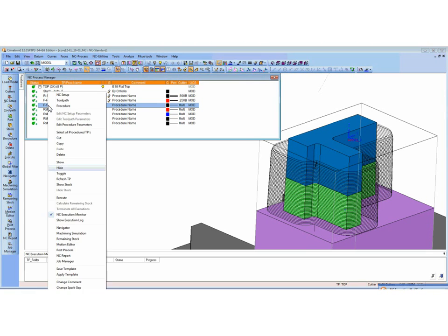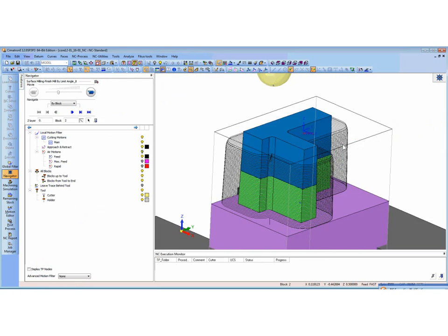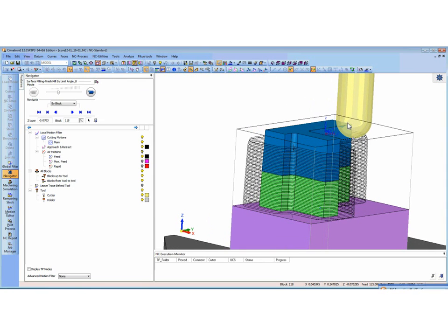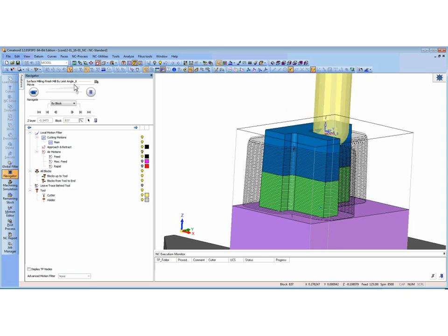Okay, yeah, so what we want is we want the tool to start nice and deep on account of being a ball cutter. There's no point starting at the top. And it's going to run around there and finish the walls doing a constant helical motion all the way down. So it's ramping the whole time, no transition between layers, all that good stuff.